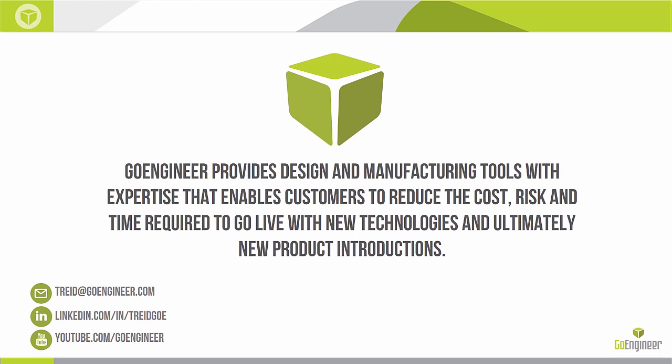They all do collision checking with the tool, the shank, the holder, but also the machine components like the spindle, air blast, any sort of fixturing, the trunnion, anything that you can model up and see, it's going to be simulated. The goal here is to spend maybe a couple more minutes at the computer, but eventually moving to the machine quicker and being able to jump into actual machining and creating chips faster.